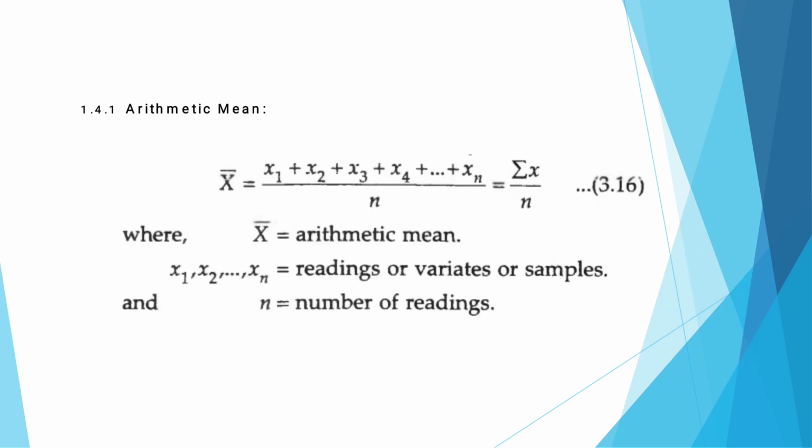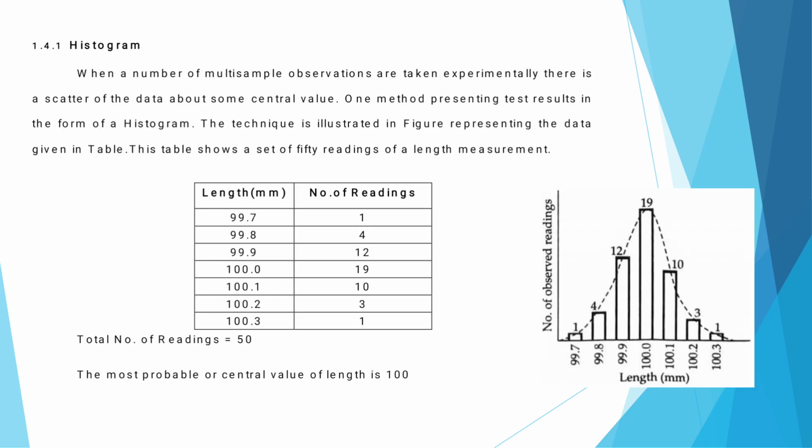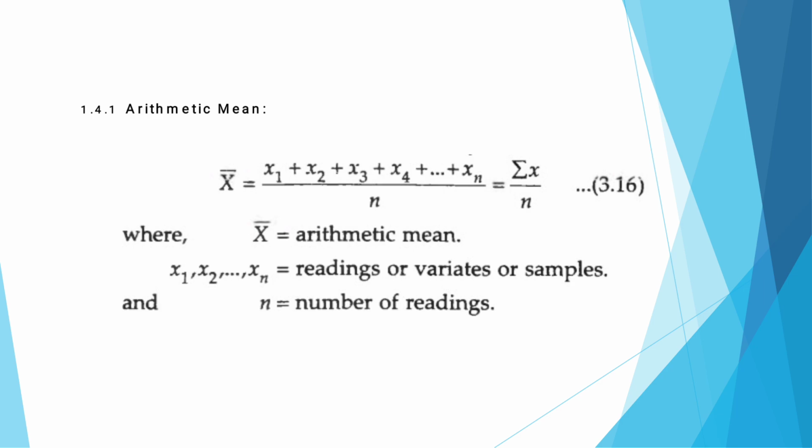And here the static performance, calibration process and the instrumentation comparison are given. All the static performance characteristics of an instrument are actually determined through this calibration process. It is absolutely vital because it gives a very important opportunity to check our instrument against a known standard, which allows us to identify inherent errors and also to verify the accuracy.